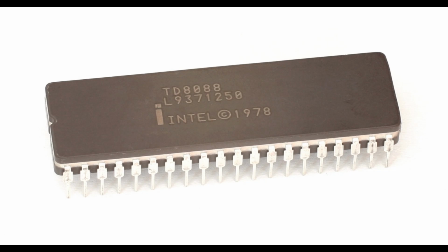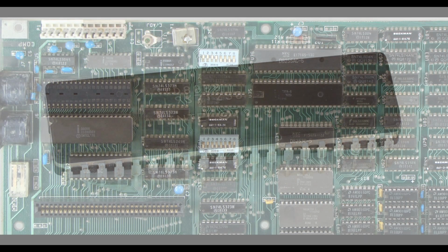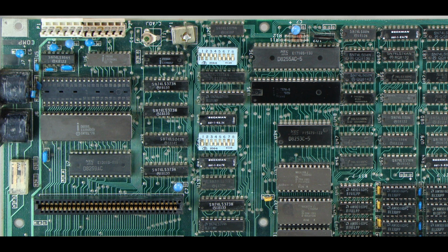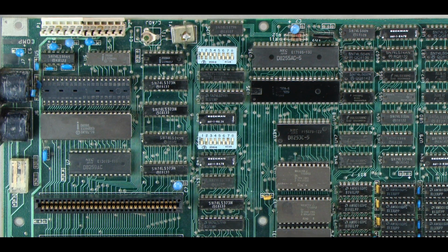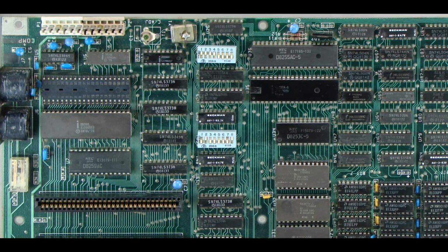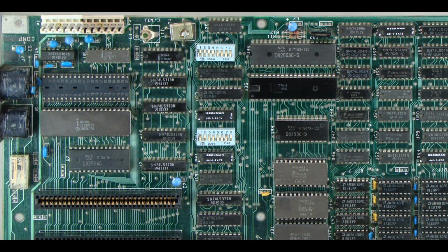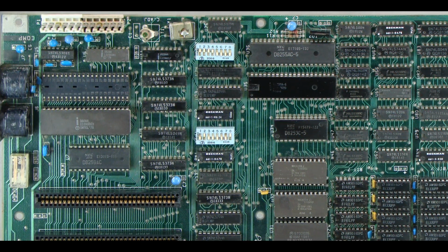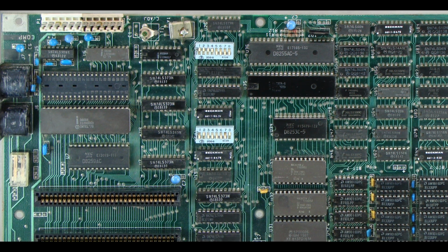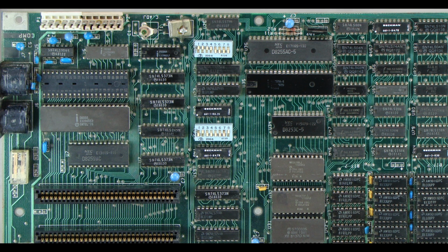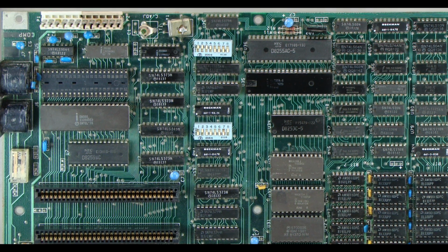As an example, let me bring up the DMA controller. It was able to handle only 64 kilobytes of memory. But it was not a problem because the motherboard of the first revision was able to host only 64 kilobytes of memory. If we take a look at the motherboard, we can say it is very similar to the first generation of 8-bit computers. It is using a bunch of TTL ICs, standard production circuits from different manufacturers, so you cannot find any kind of special circuits on board.